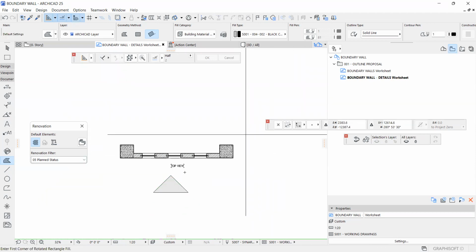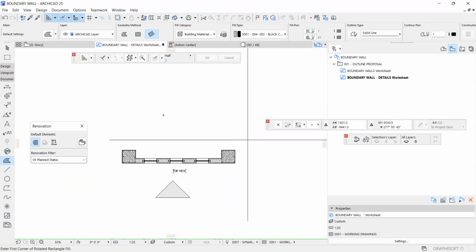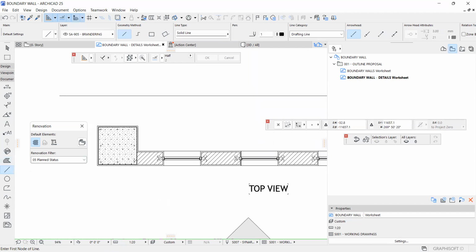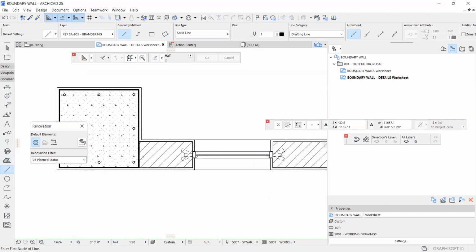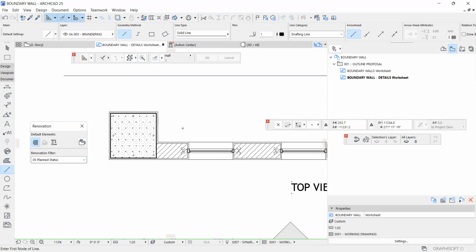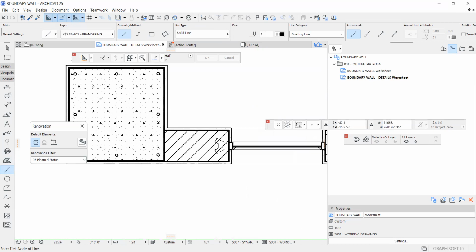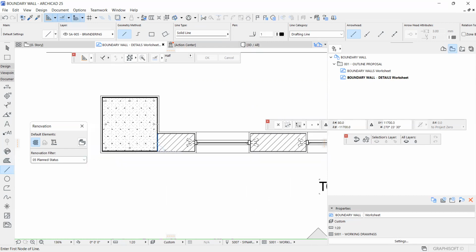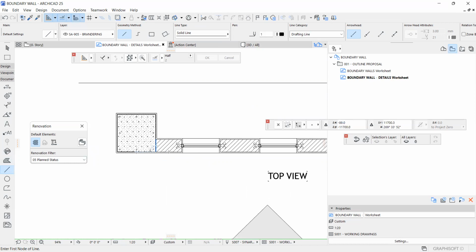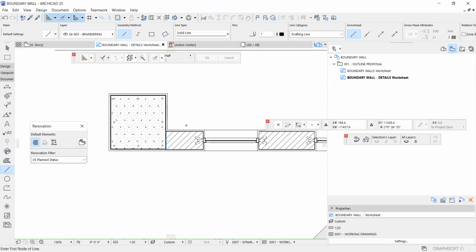Now, when it comes to the front view, there's usually two aspects. One is the projected aspect, and then there's the measured aspect, okay? So I want us first of all to project what we can see, okay? Now, this one being a plaster, we might not see that joint, okay? However, if the column was offset a little bit, we'll be seeing that, okay? So I want us to project what we see.